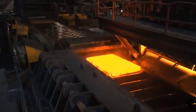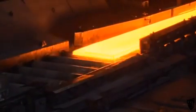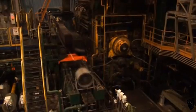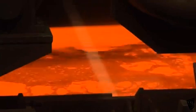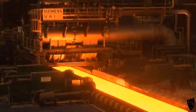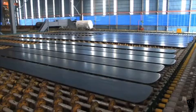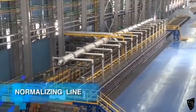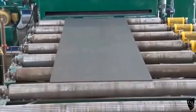Plate line 1 has 2 reversing mills that in a series of passes generate wide plate in the required thickness and width. On plate line 2, the 8-inch slab is laminated in a reversible Steckel mill, and the steel strip is temporarily stored in closed box furnaces to maintain temperatures above 1,000 degrees Celsius. Subsequently, an edger mill reduces the width of the strip to produce plate in sheet or coil. If required, the plate goes to the normalizing line, where through thermal treatment a uniform granular structure and greater hardness of the steel is obtained.